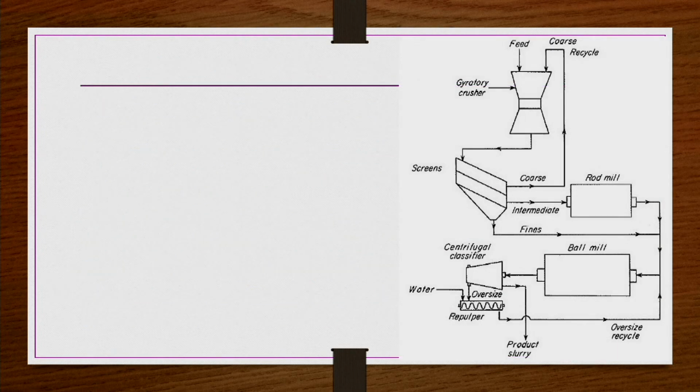Now, schematically we see how a closed circuit operation takes place in size reduction mills. Let us say we have very big particles, material directly from the mines, in big lumps like 1500 mm, 2000 mm size. Those can be taken into gyratory crushers, for example. There the size reduction is taking place. Whatever product comes from these gyratory crushers, you can pass through screens.